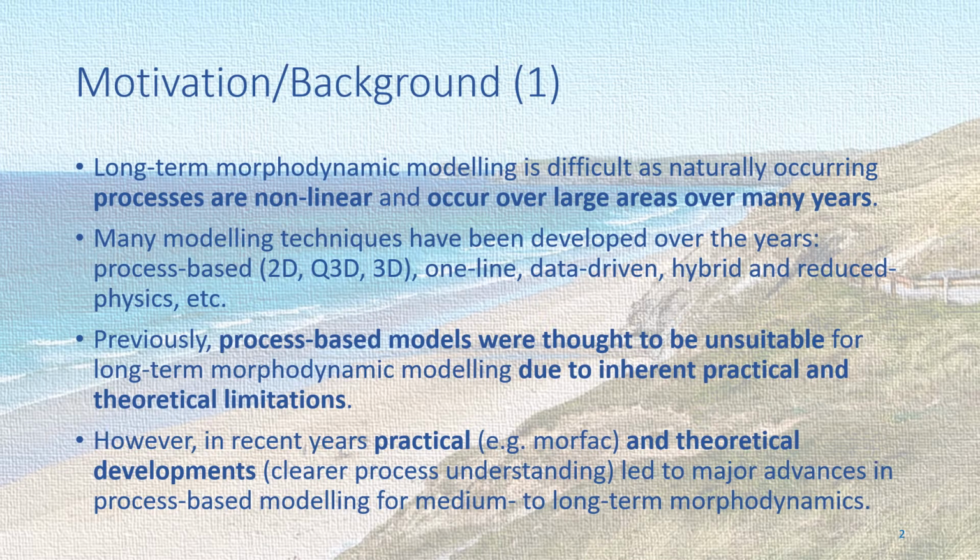Long-term morphodynamic modelling is difficult as naturally occurring processes are non-linear and occur over large areas over many years. Many modelling techniques have been developed over the years. These include 2D, quasi-3D and three-dimensional process-based models, one-line models, data-driven models, hybrid and reduced physics models, etc.